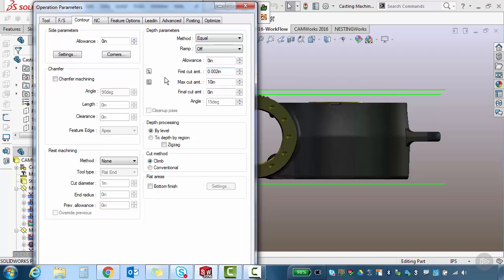By default, as this one was set, it was set to 10 inches. This can vary. But one thing to make sure of is that if this button is on, this is a percentage of the depth. I generally always work in how far I want it to go, because in my mind I know if I'm going to cut 3 inches deep, maybe I want to make the first one at 10 thousandths. So it'll make a 10 thousandths pass.